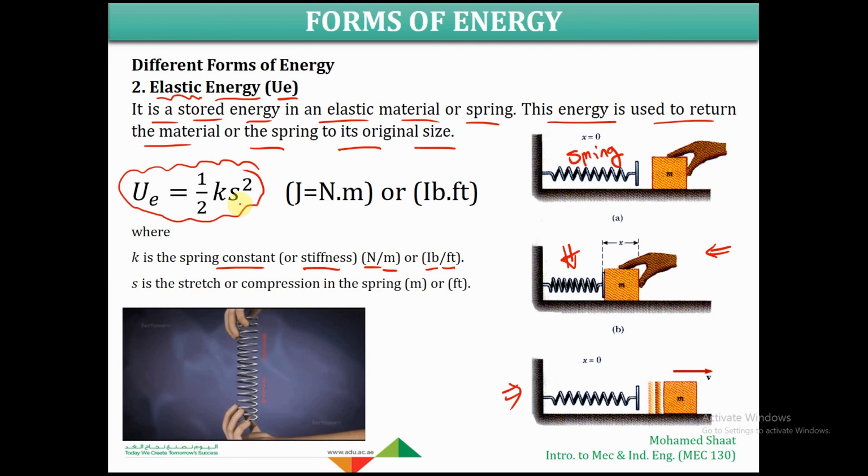S stands for the amount of stretch or compression. As we explained here, we explained how the energy is stored in the spring under compression. The same thing still applies in case the spring is stretched. So no matter what, whether the spring is under compression or under stretch, tension, the amount of stretch or the amount of compression should be measured as a distance. So this is like x here. So this x is the s in this equation.